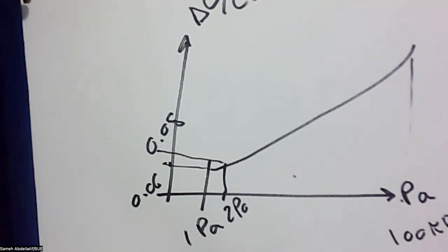You can go to the lecture where we demonstrated different interfacing circuits. You can propose from your side different capacitive interfacing circuits, and then start evaluating them: what is good, what is bad, the pros and cons. Maybe some of these circuits will be very simple, but they have a problem regarding loading. Others may be a bit more complicated, but will use more power and more energy in order to operate. You can demonstrate this investigation, or discuss it in a very detailed manner, when you do this with different topologies.